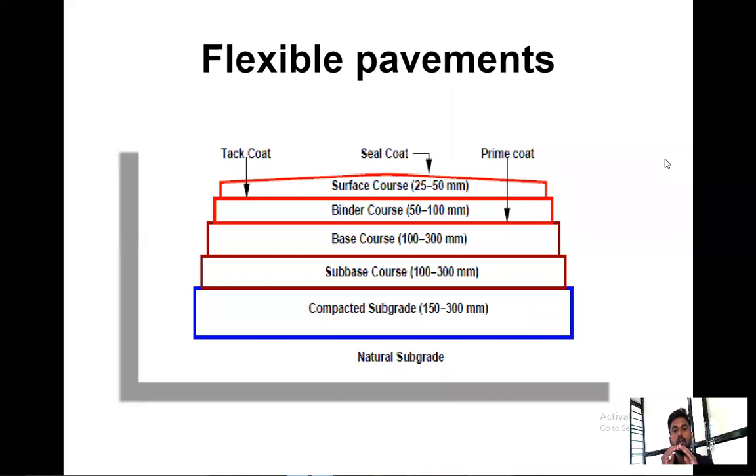It will get damaged in the foundation. You might have seen that if there is a low bearing capacity of the soil, the foundation will get settled down. Likewise, if the foundation soil is not good, the road pavement also will get settled there. And if the road pavement gets settled, what will happen? Ultimately, there will be cracks on those roads.